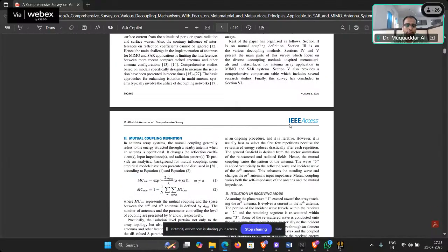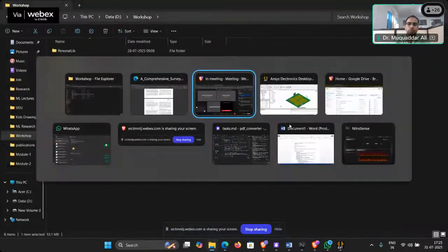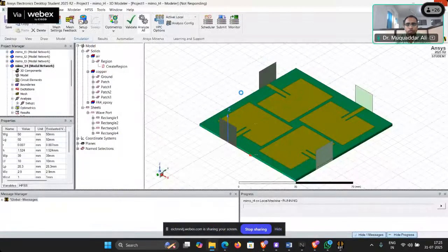So the problem with our design was, when we are rotating this, how much rotation can we give? We can make a maximum of four combinations like this. So we can have up to four cross four MIMO antenna, and all of them have different polarization.